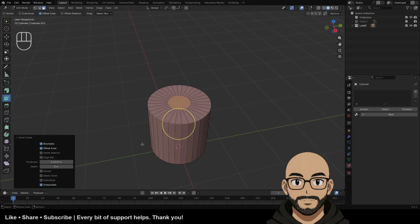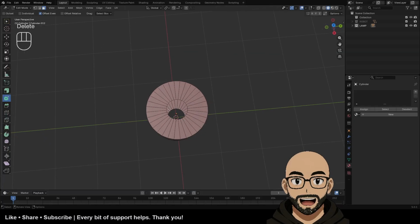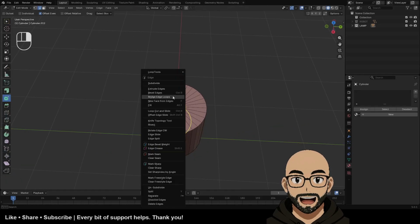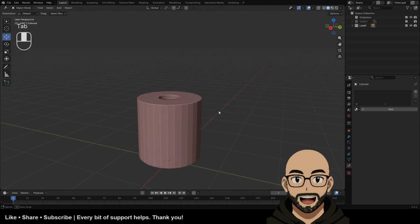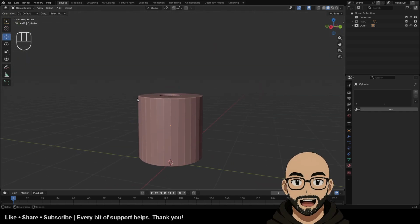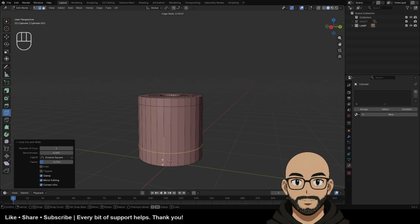All right. I'm going to say delete faces, and then I want to bridge these. I don't want it to be hollow like that, so I want to bridge it so we don't see the inside of this. So right click, bridge edge loops, so that's nice. And then what we're going to do is pull this in, so we're going to add an edge loop at the top and the bottom, and we're just going to scale it in. So I'm going to add an edge loop here, edge loop here.